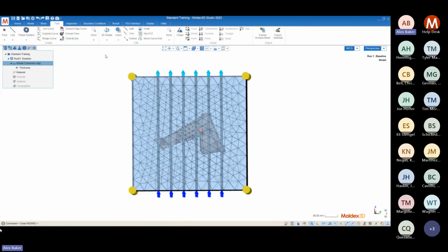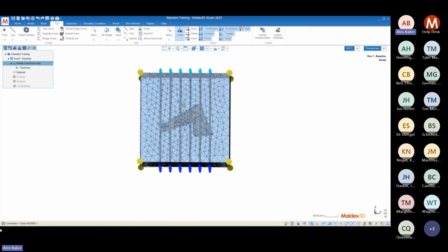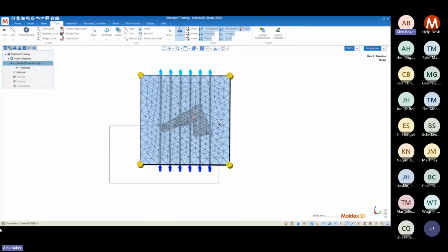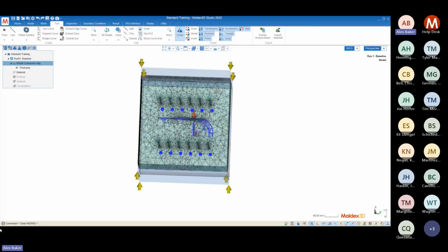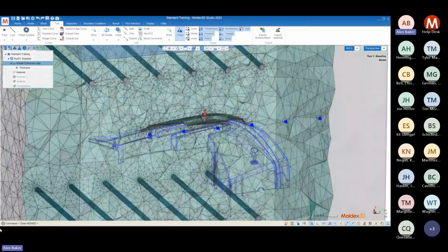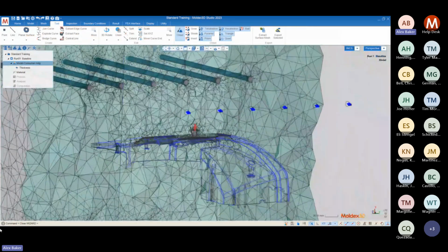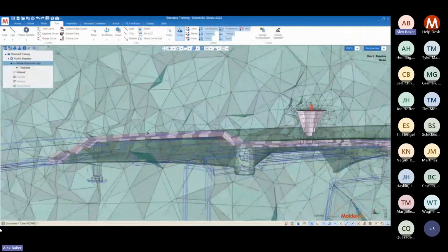You can see a bunch of creating line functions, surfaces, interactions, rotation functions, all those sorts of deals. But over towards the right, there's a chisel function. I'm going to use the chisel function. The way that this function works is I'm going to left click, drag a box. Any element contained within that box is going to be temporarily hidden. And it allows me to see the styles of mesh that are created for each different part of my geometry.